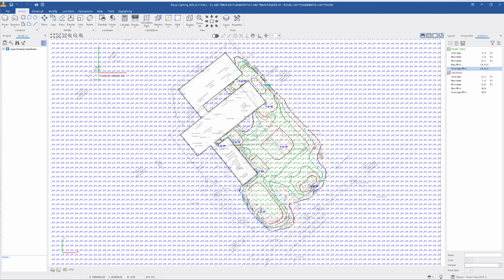This is a strange place to put it. I still haven't figured out why they do it this way. But you actually go to print is the next thing you would want to do. And it usually comes up with a blank page with their title block on it. So when you have that, you can go to clear and gets rid of that. Typically all I ever use this for is to get the schedule, which is this button right here. That puts our light fixtures out there, but it always comes with all these extra columns that we don't typically use. So I can get rid of that.